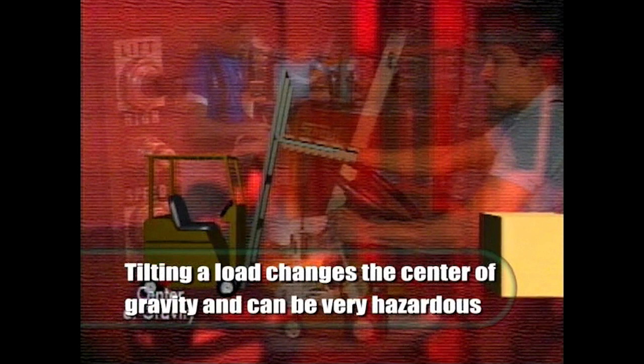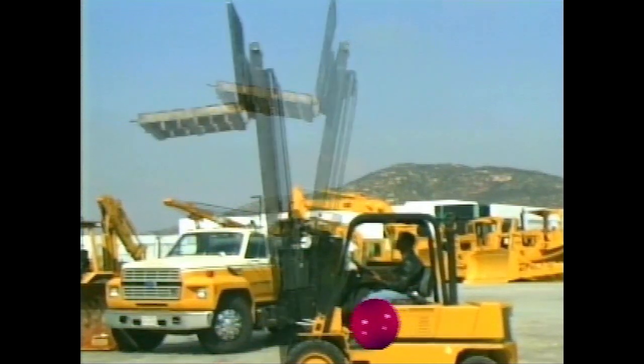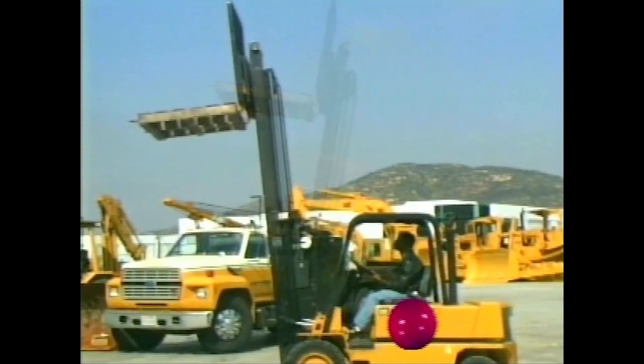That's why tilting a load while raised can be a major safety hazard. Tilt loads only when safe to do so and necessary for positioning loads onto racks or other material handling equipment. Of course, you're changing the center of gravity even more when you tilt loads. Tilting a load changes the center of gravity, and this can be very hazardous to your safety if you exceed the maximum safe lifting capacity of your particular forklift. Moving loads upward, downward, forward, and backward causes a shift of the center of gravity and can adversely affect the vehicle's stability.